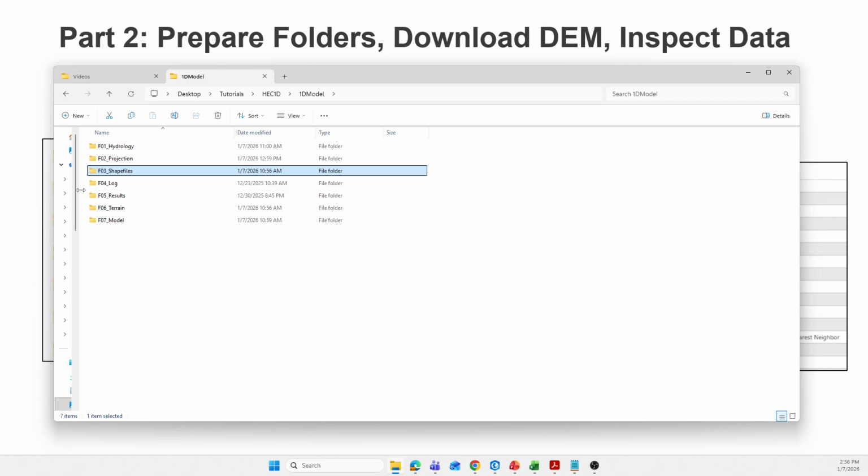If we have the bridge line work or measurements, we can also draw those lines ourselves. We can bring those shapefiles here. Those shapefiles we are going to import into HEC-RAS, so HEC-RAS will be able to guide us on how we want to place our lines.